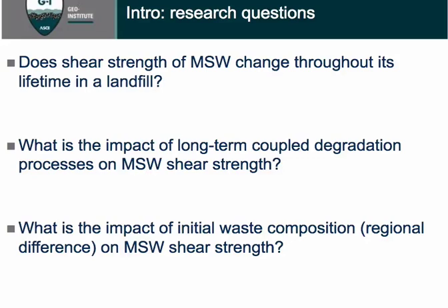So our research questions here at the University of Michigan are, first, does shear strength of municipal solid waste change throughout its lifetime in a landfill? Because when the waste is disposed of in a landfill, it stays there almost forever, for decades or even up to centuries. So the change in shear strength is definitely one thing we need to take into consideration during our design.